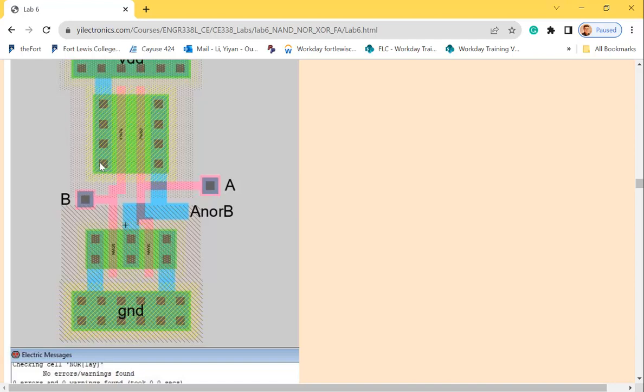Okay, is this metal one? Yes, because the transistor, this is the transistor, is at the bottom of the layer of the entire thing. And it's drilling holes to the top and connect all the diffusion, the N plus or P plus. This is a P plus. Drill the hole to metal one. That's the only layer. So from the diffusion,